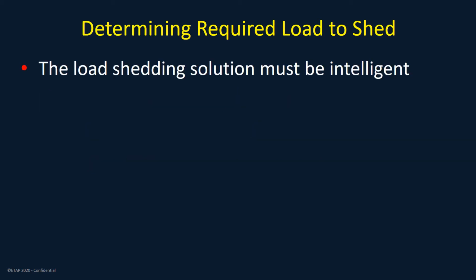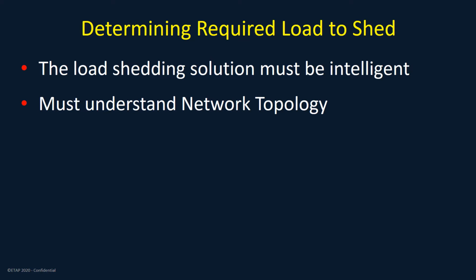To calculate the required load shed under different conditions, such as overloads, under frequency, under voltage, the solution must be very intelligent. Distribution networks, although most of the time operated radially, can change topology during reconfigurations during maintenance procedures. Changes in the topology can happen at sub-transmission systems. The load shed system must have visibility of the entire network. Topology changes might cause loads to switch feeders, create unbalance and/or overloads even at the sub-transmission side.